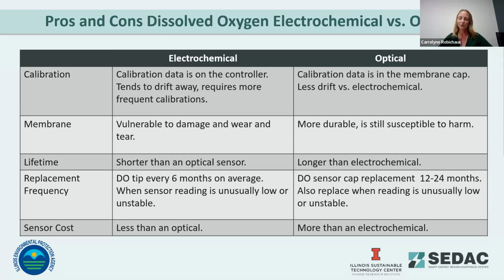The only application I've seen where an optical probe didn't work was because they had grit in the aeration basin. I think their plant had other problems. I don't know how the grit gets there. It would actually rip up the sensor, the membranes.